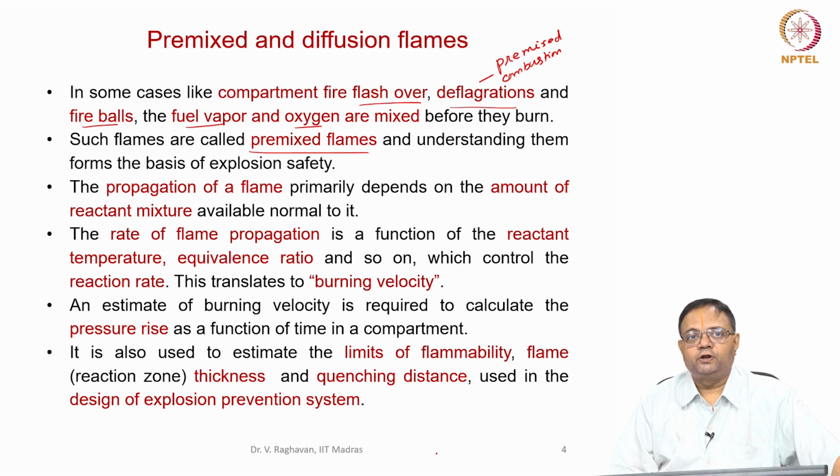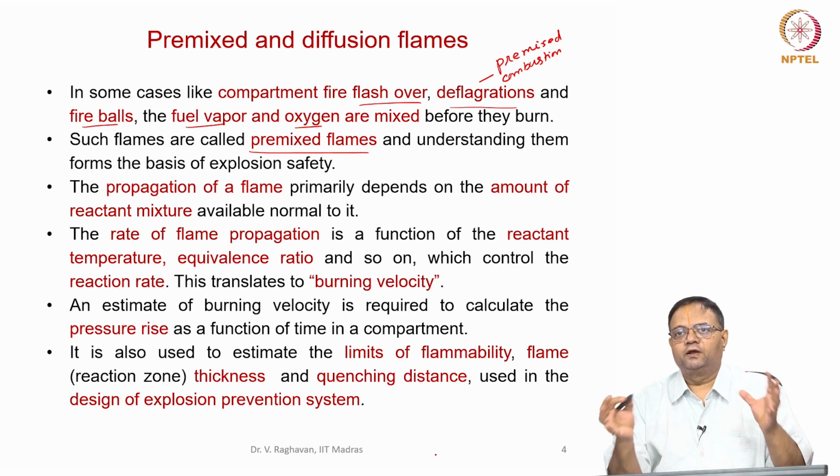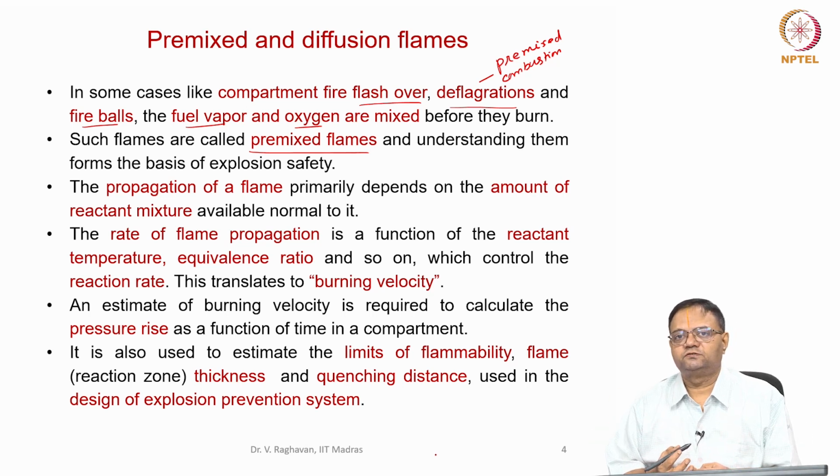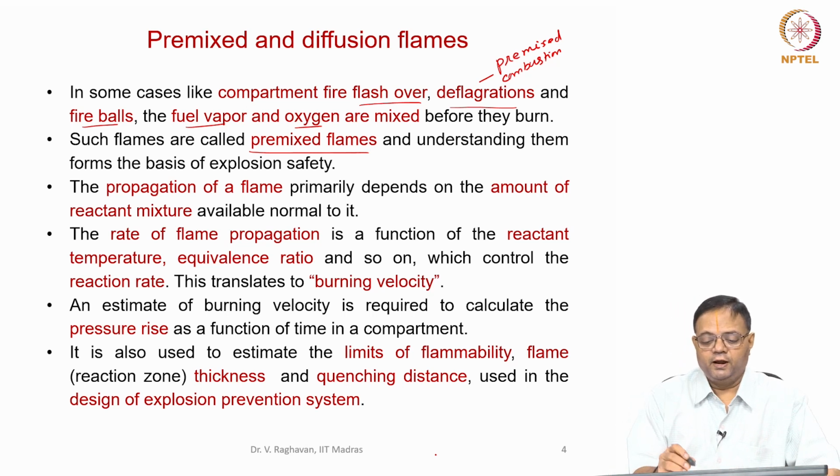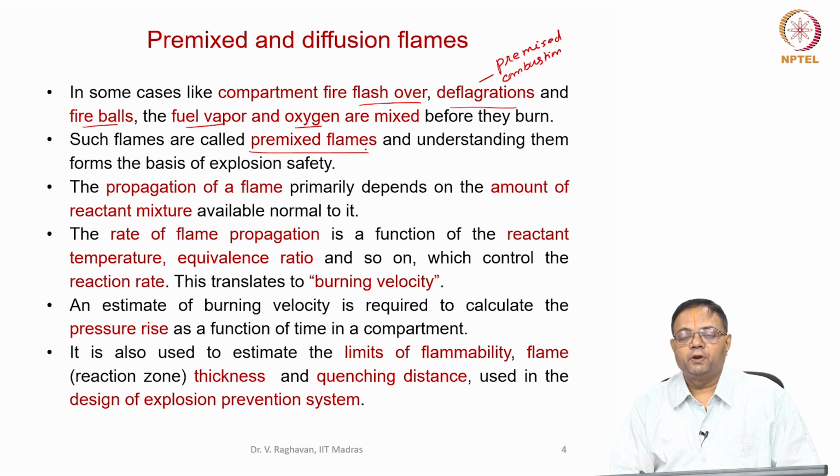And also, if you take some explosion compartment, for example, a spherical volume where we do tests for flammability or flame speed measurement, you will see that pressure build-up can occur here. So, to understand the explosion, the pressure rise due to it, and to plan explosion safety features, we need to understand the characteristics of premixed flames.